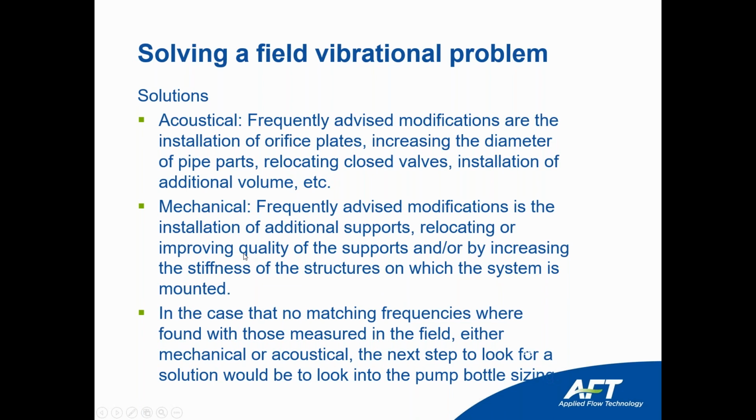Sometimes you might be using supports that are too flexible and they're easily excited. If they're too flexible, they're not an effective dynamic restraint. So the system will vibrate. So you might want to increase the stiffness of the support to assure that it constitutes a dynamic restraint.